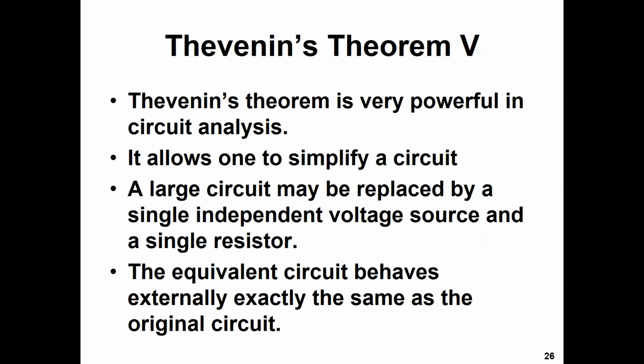Okay, Thevenin's theorem is very powerful in circuit analysis. It allows one to simplify a circuit. A large circuit may be replaced by a single independent voltage source and a single resistor. So this is the beauty of the Thevenin. Just a complicated, large circuit, we can replace by two elements: an independent voltage source in series with a single resistor.